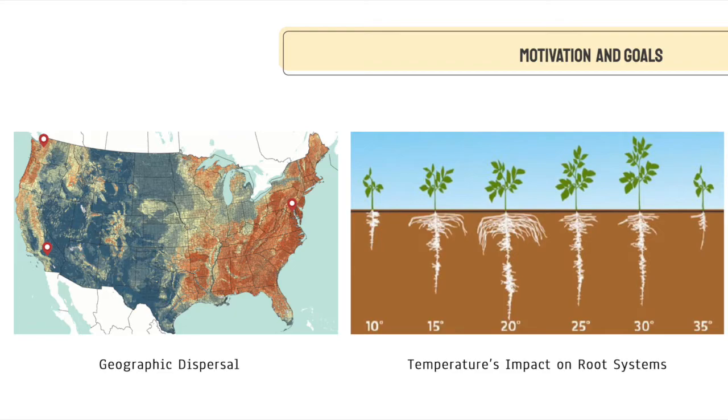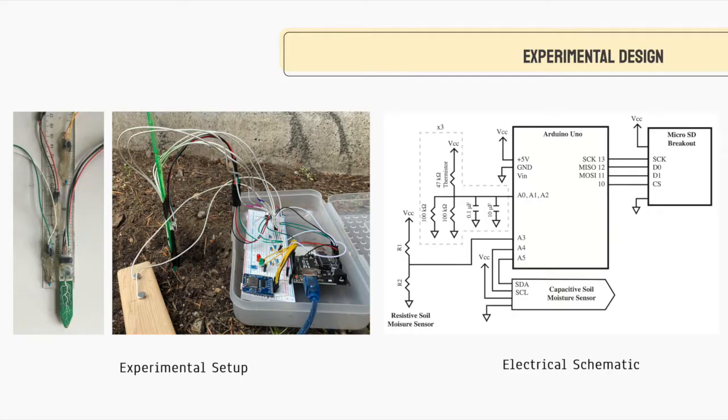By identifying how our respective soil types filter out high and low frequency changes, we can hope to provide a better understanding of which environments might sustain certain plant life better than others. The team carried out multi-day deployments to measure temperature and moisture. Three thermistors were hot glued onto a ruler and buried at the surface, 2 inches, and 4 inches deep to see the filtering effects of the soil.